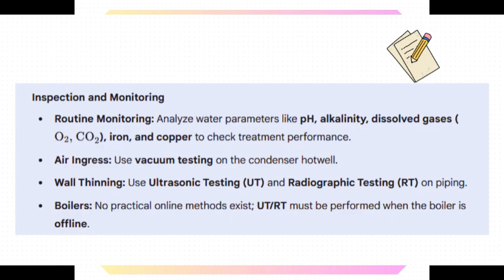So wrapping this up, what's the big picture takeaway for someone managing or working with these systems? I'd say managing boiler corrosion isn't a set-it-and-forget-it task. It's a constant balancing act. Right. You're juggling precise chemical treatment, smart physical design to minimize those flow disturbances we talked about, and choosing the right materials. And constantly checking. Sampling, analyzing, adjusting, and using those precious shutdown windows wisely for inspection.